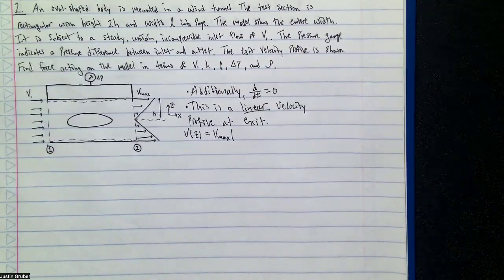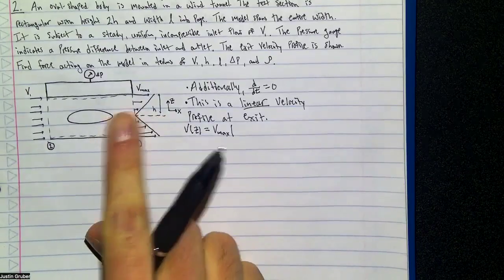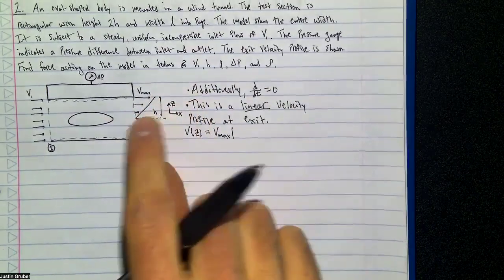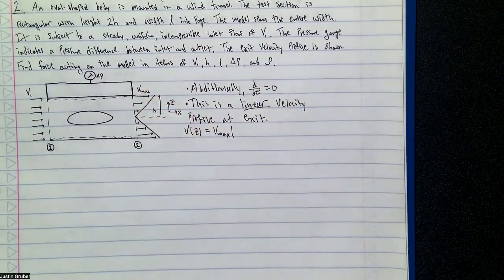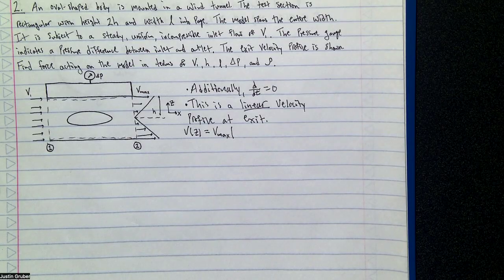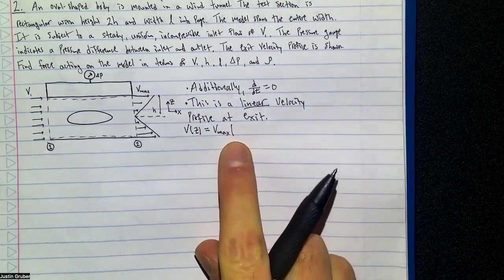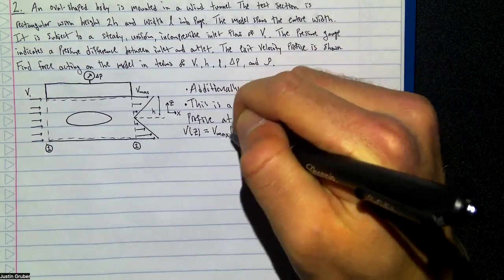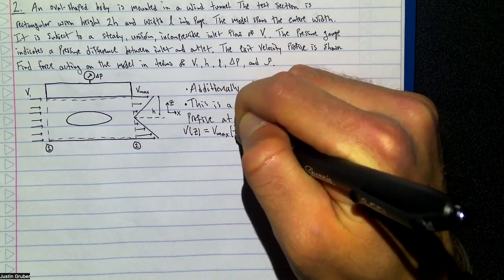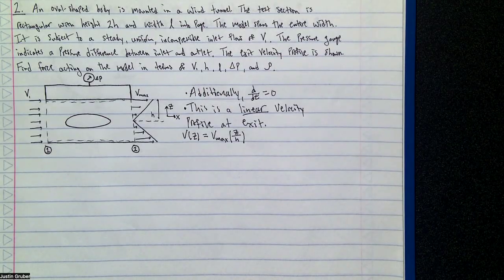And there's two different relationships you can get with this. If it was the inverse of this situation, like a cone coming out, where it was maximum velocity in the middle and then tapered down to zero at the edges, like coming out of a pipe, because of the no slip condition, the velocity right at the pipe edge has to be zero and it's max in the middle. This is the opposite of that. If it was that pipe flow one, it would be one minus Z over H. In this case, it's literally just V max times the ratio of Z to our height H, where H is just the total height of the thing.